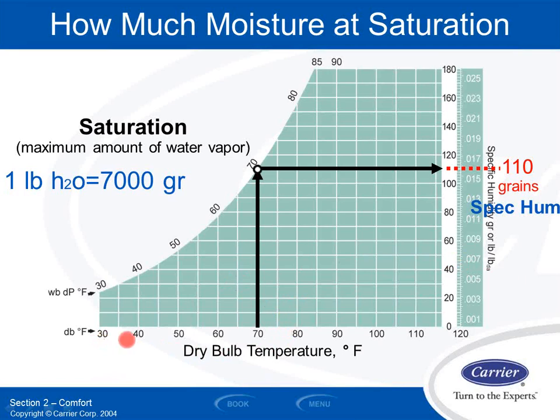So down the bottom axis, we have dry bulb temperature. And in this case, the chart goes from 30 to basically 115, 120 degrees on the chart. Up the vertical axis, we have the moisture content, and it goes from 0 to 180 grains of moisture on this particular chart. That's all my actual water moisture. So it's my specific humidity, my actual humidity. I'm adding up all those moisture droplets. On this chart, there'll be curves eventually as we talk further with humidity percent on them.